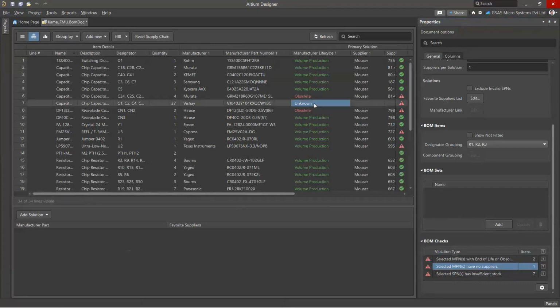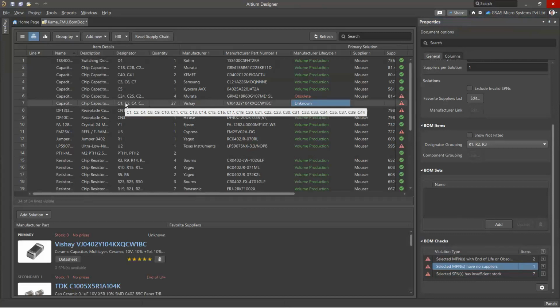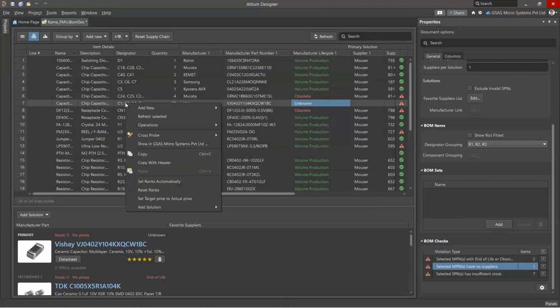If you want to look at this particular component, which, as I told you, has been placed from Altium 365, and you want to navigate into Altium 365 to see where it is being used, right click on this and click on the option showing the name of your workspace. Altium 365 helps you manage your data in the cloud. Apart from the data, you can manage your components in the cloud. I have the pro subscription, which enables me to manage my libraries in the cloud.